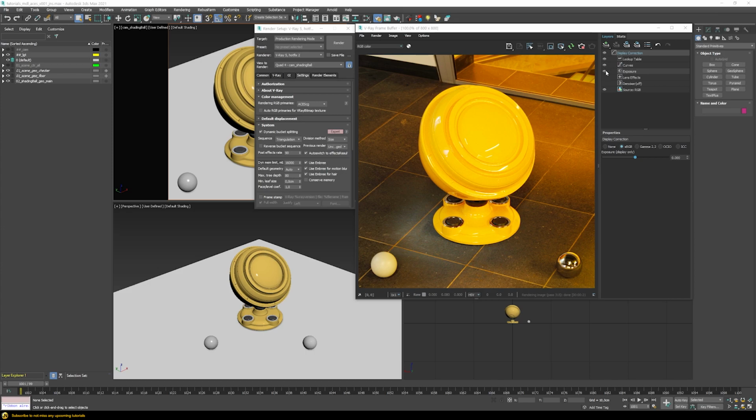So now back in 3ds Max, we don't need these kind of adjustments that I added here before, because all of those would now be done internally with our OCIO file. So once I finally switch to this OCIO, it would then load the file from the environment variable that we set before. And then there are different options you can choose here. I chose, for example, to set the input color space to ACEScg, which makes sense because that's what we're rendering here. And then display device, there's no option right here, but view transformation, you should most likely choose sRGB, because you're most likely looking at it on an sRGB monitor. So then you can get some photographic final looking result with this kind of configuration.